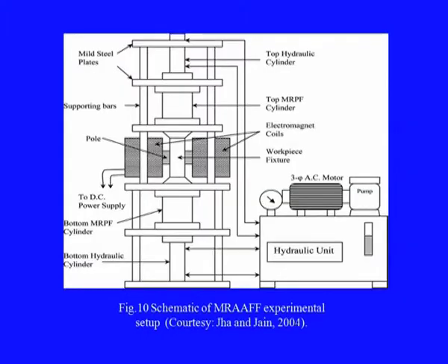In this process, rheological properties of an abrasive laden medium, also called smart magnetorheological fluid, is controlled using an external magnetic field. It imparts better control of the process behavior due to better control over the abrading medium's rheological behavior. This is the schematic of this process.